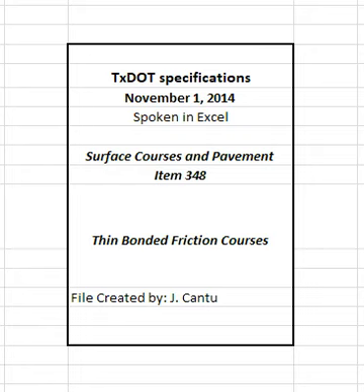4.7.3.2 Hauling equipment. Use live bottom or end dump trucks to haul and transfer mixture. However, with exception of paving miscellaneous areas, end dump trucks are only allowed when used in conjunction with an MTD with remixing capability or when a thermal imaging system is used unless otherwise allowed.